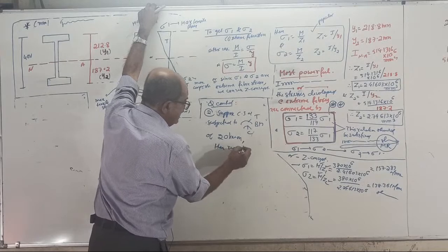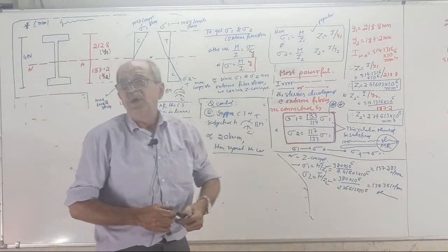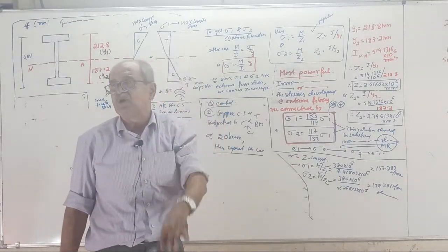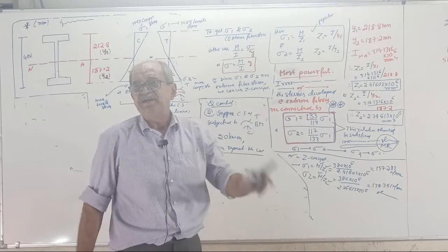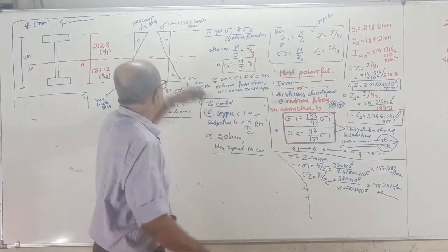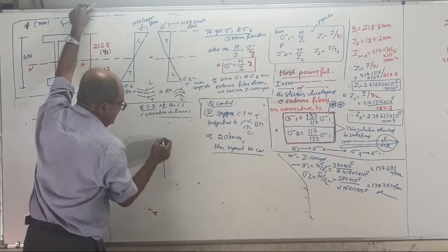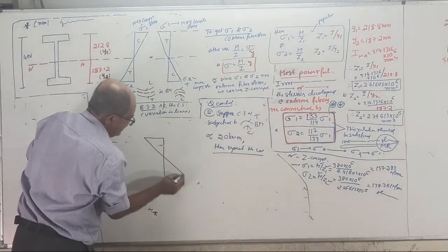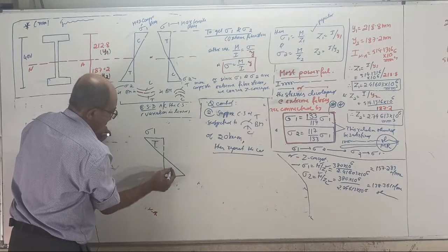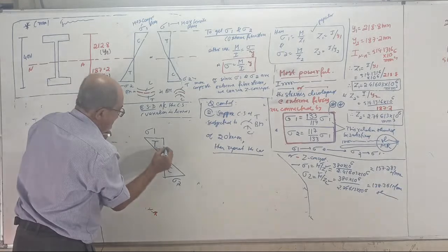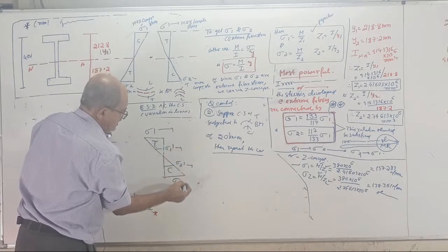Right. 20 kN meter hogging, then repeat the calculation. That is same question. What do you have to do? Draw the bending stress distribution across the cross section. Decide maximum compressive stress. Decide maximum tensile stress, and tell where they will take place, and also tell what are the stresses at 100 mm inside. Fast answer. See, answer is, now it will come like this. This is your sigma 1, now not compression now. Now it is tension, this is compression. Sigma 2 somewhere here, sigma 1 dash somewhere here, sigma 2 dash. Fast get the answer.